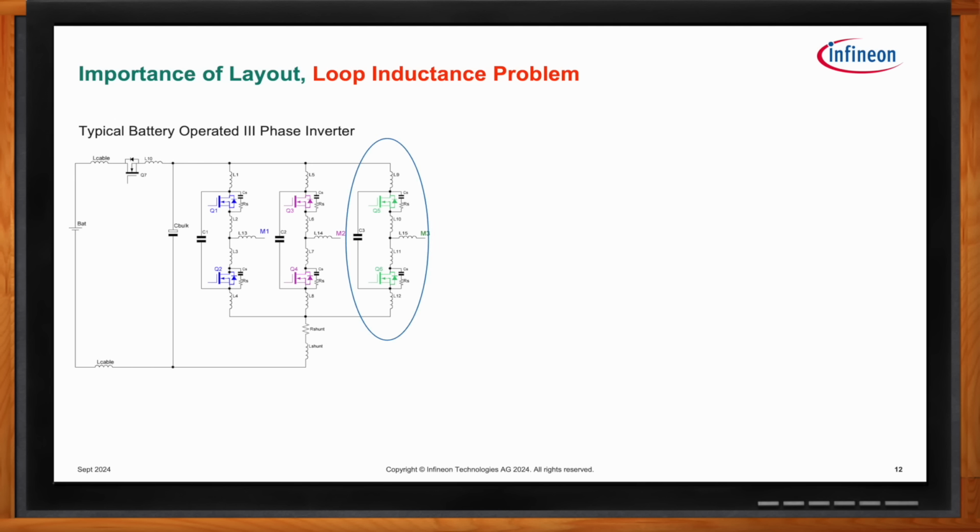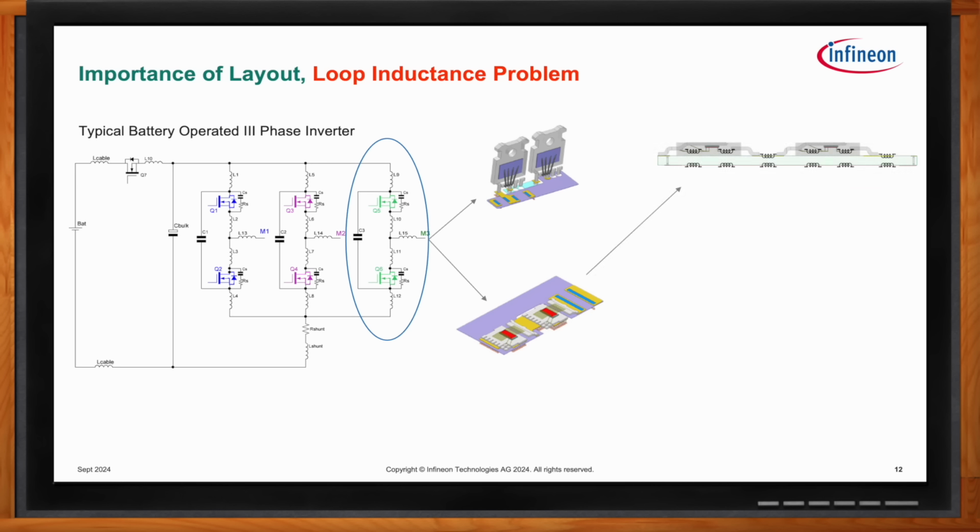At the PCB level, such a half bridge is constructed using either through-hole or surface mount devices as shown here. Given its unique physical layout, each half bridge design will end up with a certain cumulative loop inductance, which is a summation of PCB trace inductances as well as parasitic inductances internal to each device.